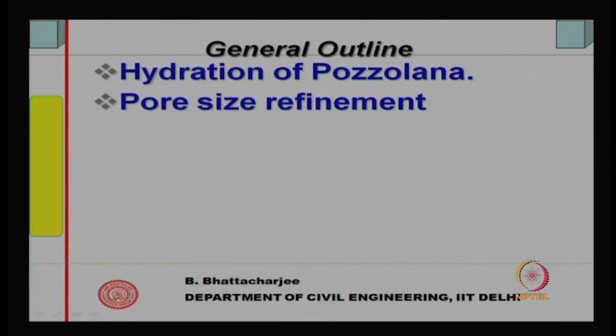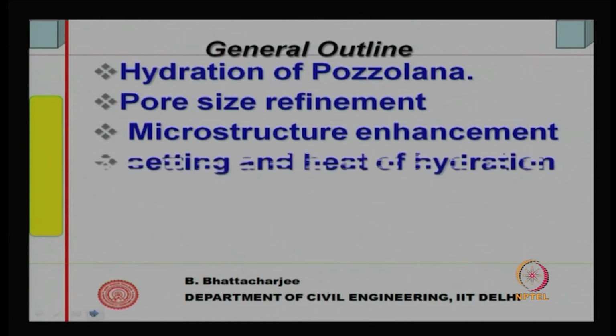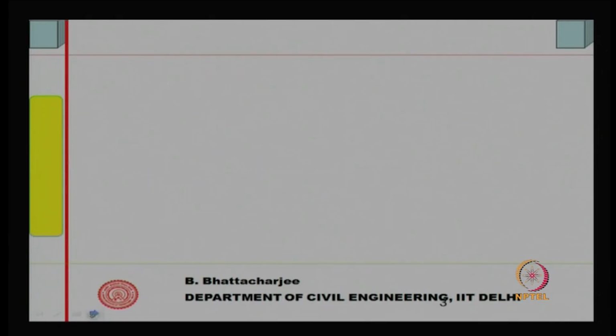We will look into the way they refine the pore size of the cement hydrates and the improvement in the microstructure that they bring about in cement paste, mortar or concrete, and then setting and hydration of this material, their water demand in the fresh state, etc.